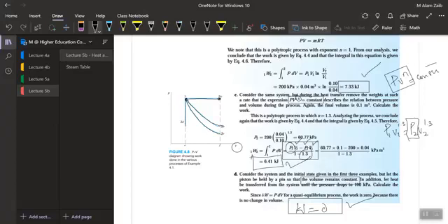So if you look at it, the maximum area possible would be under the constant pressure process. Then we have got the isothermal process, and later the polytropic process, and obviously there is no area under the curve in a constant volume process.